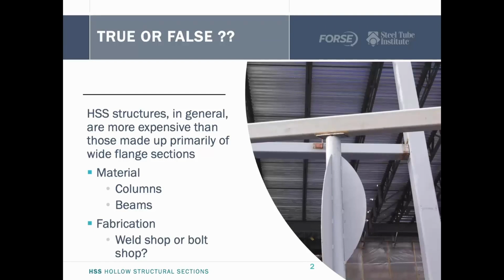Different fabricators have different thoughts on HSS. Some of them are set up to bolt everything in their shop, like their beam lines are set up to bolt, and so therefore they're less, I would say, HSS friendly than those that are set up to weld.